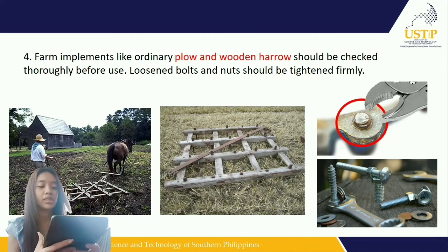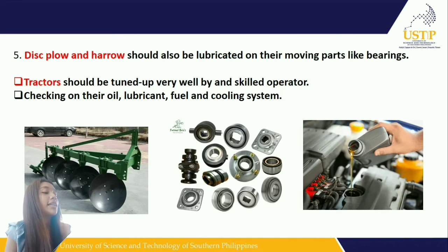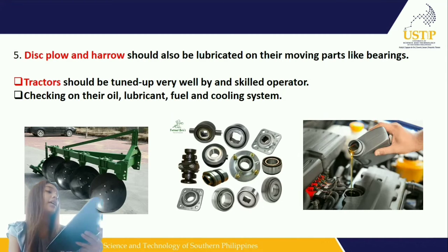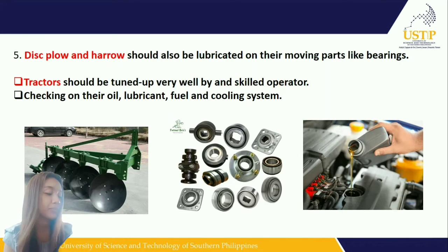The fifth one is this: plow and harrow should also be lubricated under moving parts like bearings. Tractors should be tuned up very well by a skilled operator, and checking on their oil, lubricant, fuel, and cooling system.